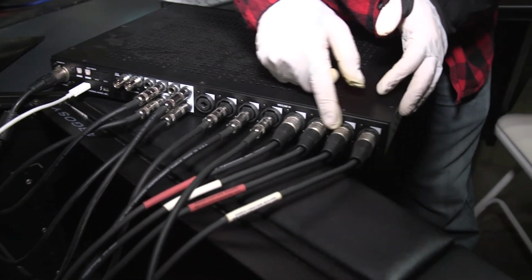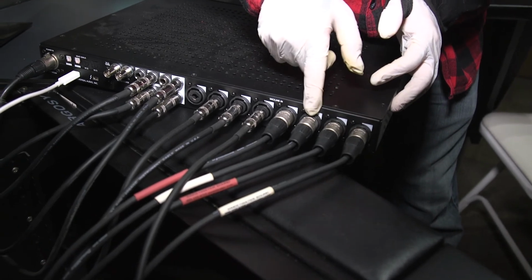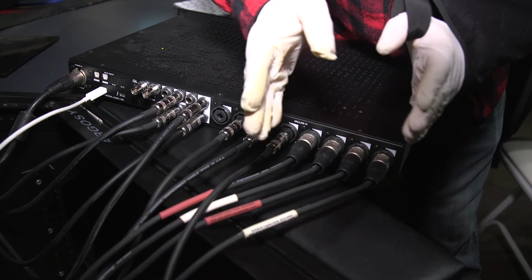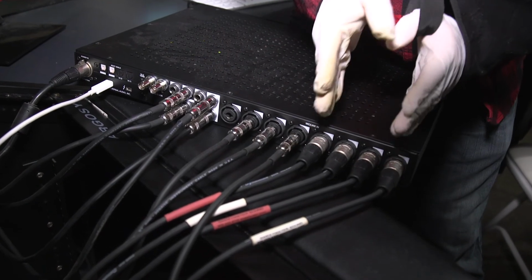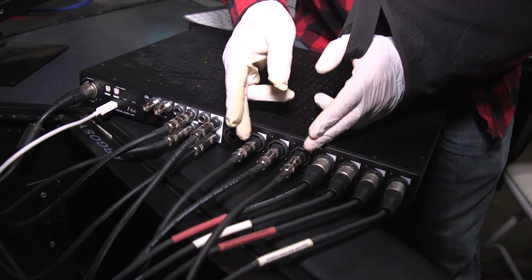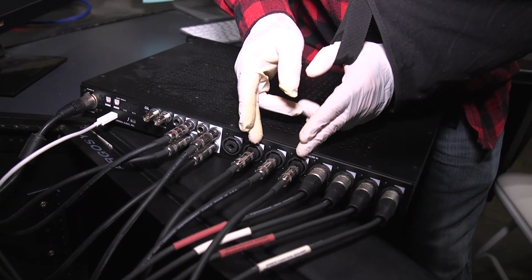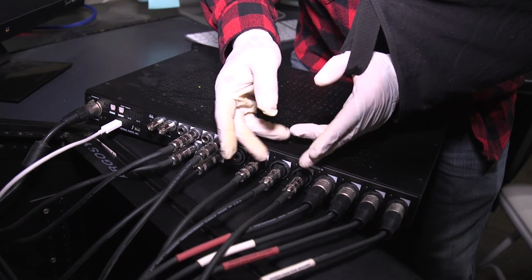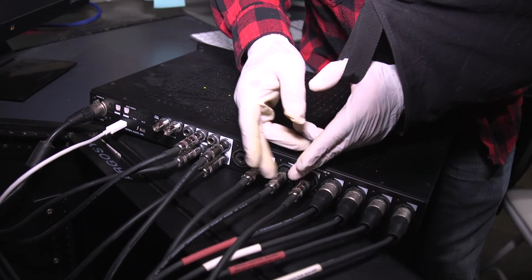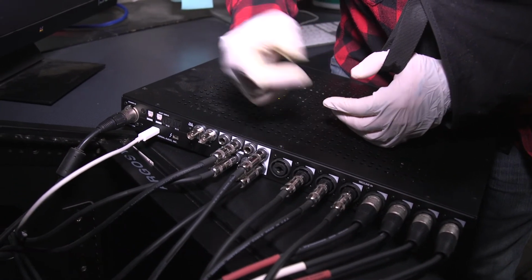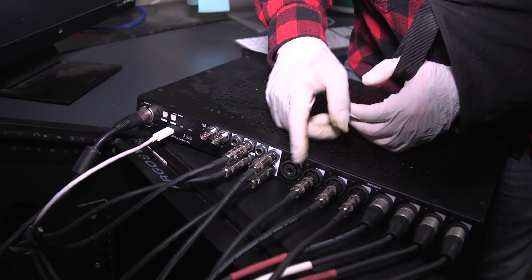So on the back side we have input 1, 2, 3, 4, and as you can see we have our 4 XLR cables ready to supply phantom power because these 4 have preamps. And then we have 5, 6, 7, which are set up for line inputs. So if we wanted to connect a guitar in the live room or whatever it is, we have the inputs for these with these 1/4-inch cables. And then input 8, we don't have anything because we used that for our headphone output.